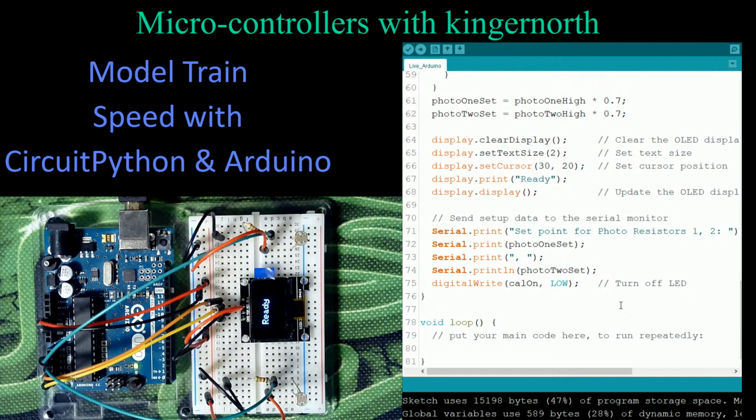Those numbers are going to range because the input value on an analog pin goes from 0 to 1023. So we're a little higher, probably about 2/3 of the way up the scale. Maybe not quite 2/3, maybe about 60% of the way up. But it shows us that we've got some good light and a good trigger point.